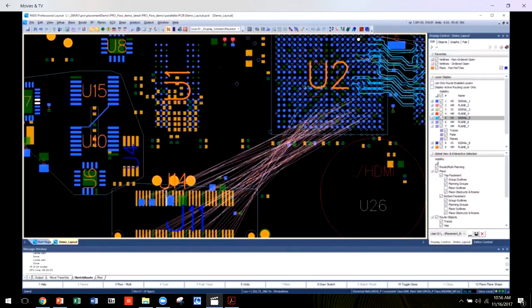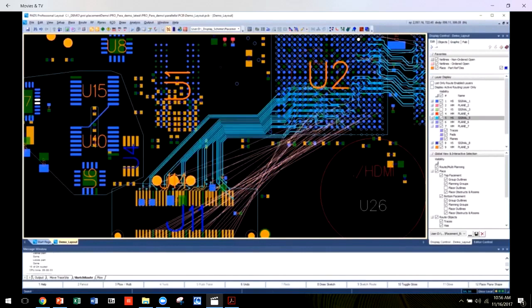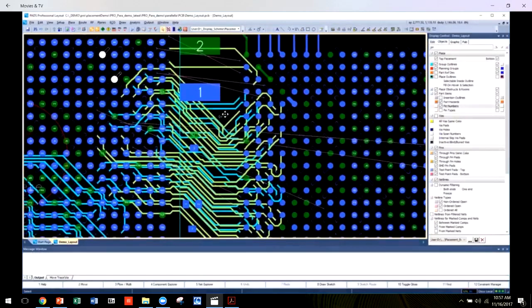By default, the sketch path is freeform. You may choose an angled sketch path using F10 toggle sketch style or right mouse button click toggle sketch style. The freeform path is best when you just want a quick path through a general area. The angled path is best for precisely placed straight paths with more specific control over meander and bend location. The routes tend to adhere more closely to an angled sketch path.